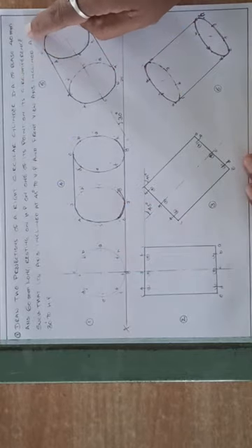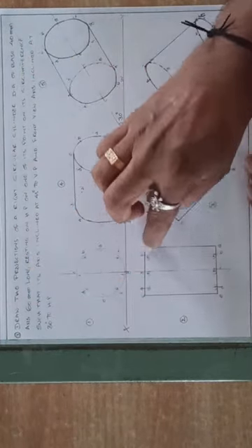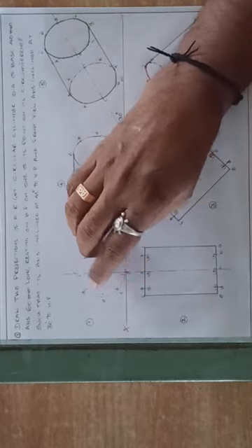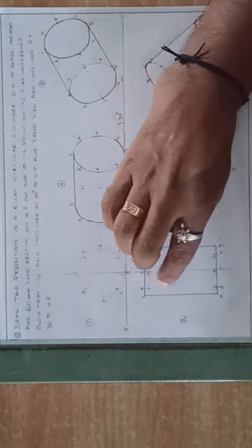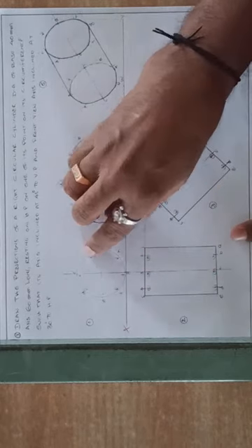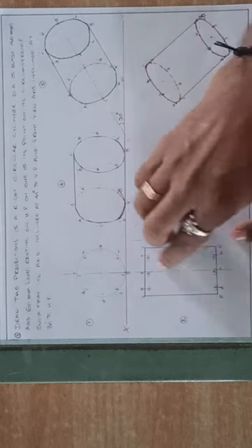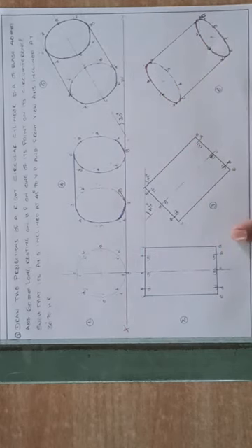Now, so how much is the length? 60 mm is the length. Project it, take the 60 mm length, mark here. Now there is no need to project all these lines. Okay, just mark the points here. From top, project the line up to the face. Okay, not necessary to join inner lines also. Even if you want to join, use very thin lines.